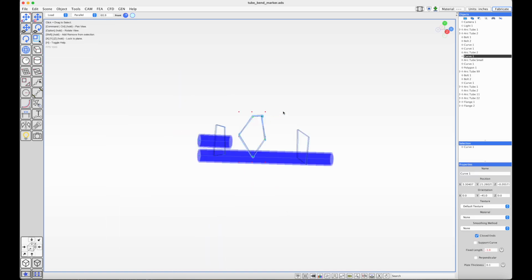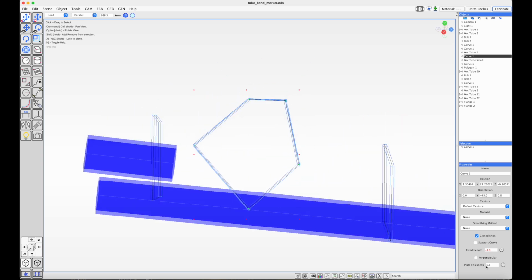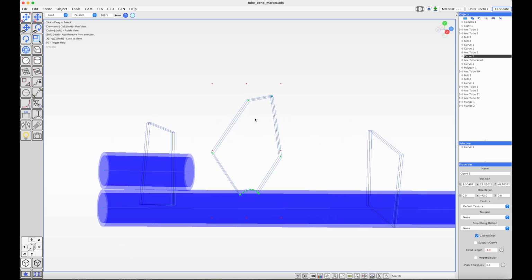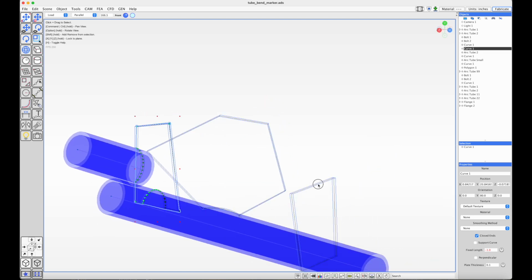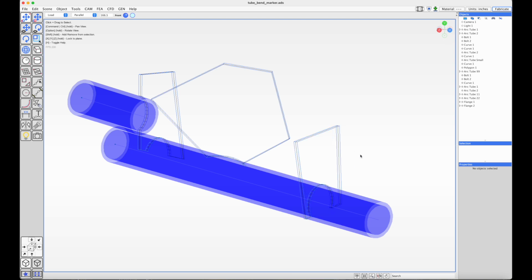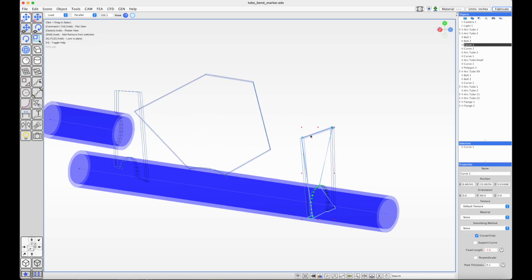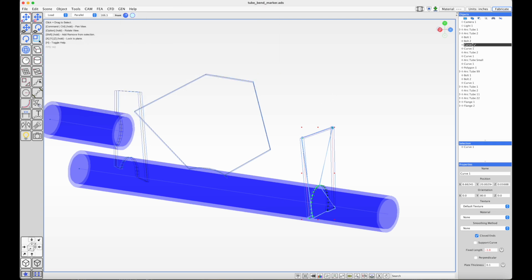So one of the other things that's relevant to plate parts that are based off of these closed curves with a thickness value is that in modeling in 3D space, we can have it interact with all of the scene elements that we want. But in order to cut it, we need to generate G code that will instruct a plasma table to cut the parts. So what we want to do is select the object, under CAM, select layout, and now it's going to put it in the layout mode. You can see it's a different color and it's indicated with an asterisk under the part number.